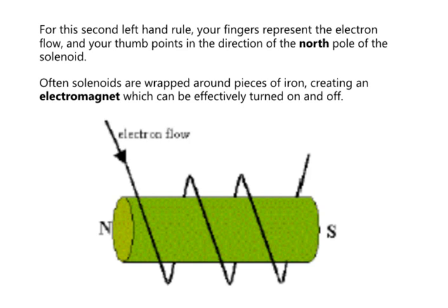Okay, so let's try this one here. If the electrons are wrapping around this way, going down, coming up the other side and wrapping around, you can set up your hand. Maybe I should go to the front even. I'm using my left hand, okay? My fingers are pointing this way, and the reason why, it's really hard to get this, but can you see how my fingers are wrapping underneath the bottom like this? When I put my hand in this really awkward scenario, these electrons are going through the bottom like that, which is why the North Pole goes this way.